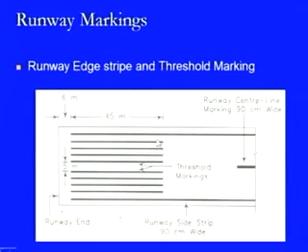These are 45 meters in length, and as we have seen, the width is variable along with the gap being provided. Here another type of marking which is shown is the edge strip marking, which, as I have told, is a continuous strip 90 centimeter wide and is located at the edge from this side as well as from this side. So, there is a pair of this marking, and these threshold markings can come within 3 meters of this edge strip marking.